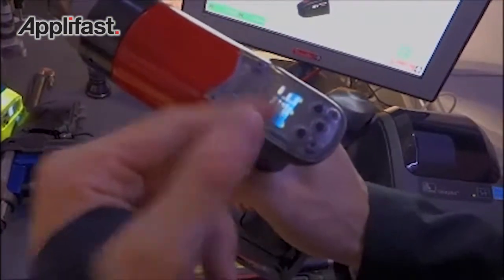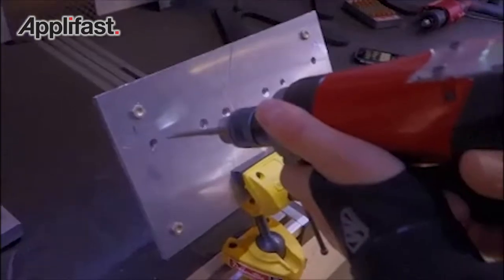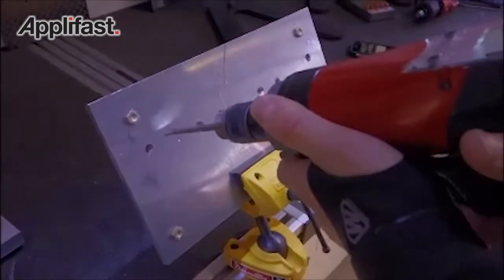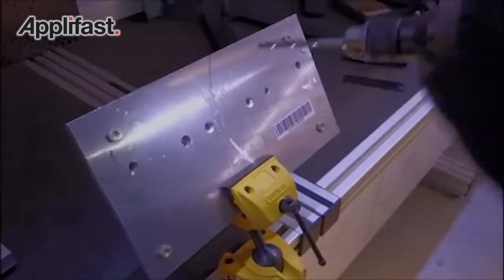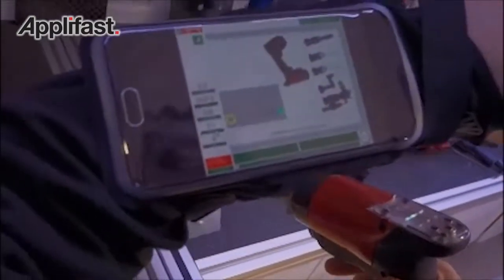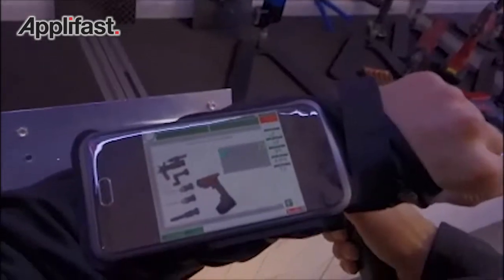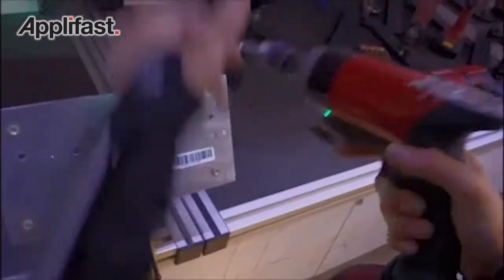In this example, this is aluminum, so we get a speed which is set up at 3000 RPM. Okay, so we will do the drilling operation. This is fake again. Okay. Drilling has been done, as you see, on the first, and now we need to enlarge the second temporary fastener hole. So I'll do my second drilling, where I've got the yellow light blinking. Okay, and then, same process, I move to the reaming operation.